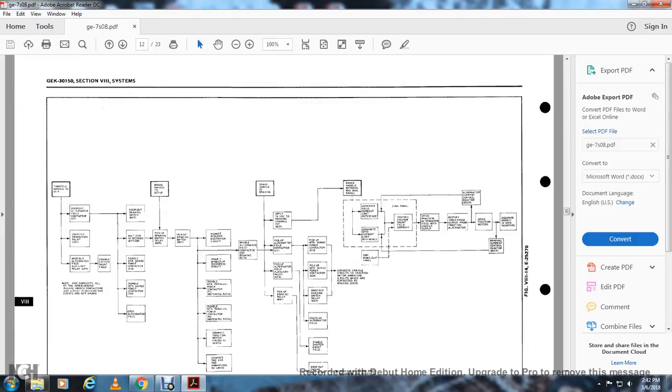Alright, you have throttle at idle, the dropout alternator field current with the dropout transition relay, dropout alternator field auxiliary relay, which disables the exciter shunt field, the dropout alternator field contactor, dropout braking switch, and then it also has the wait for 10 seconds, disable motor series with the power contactors, open alternator field.